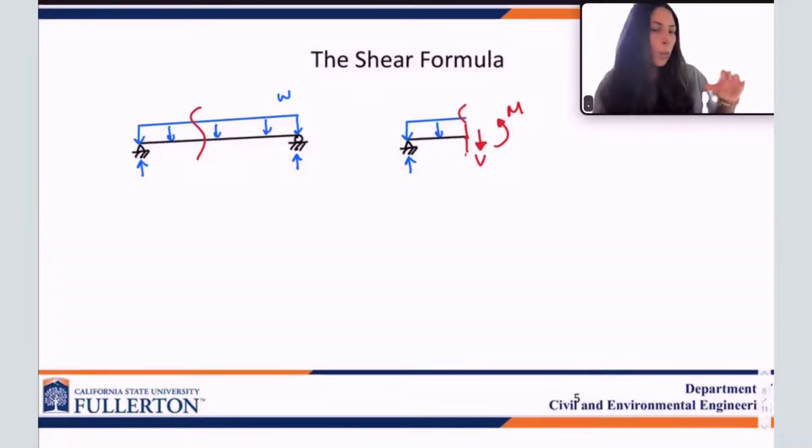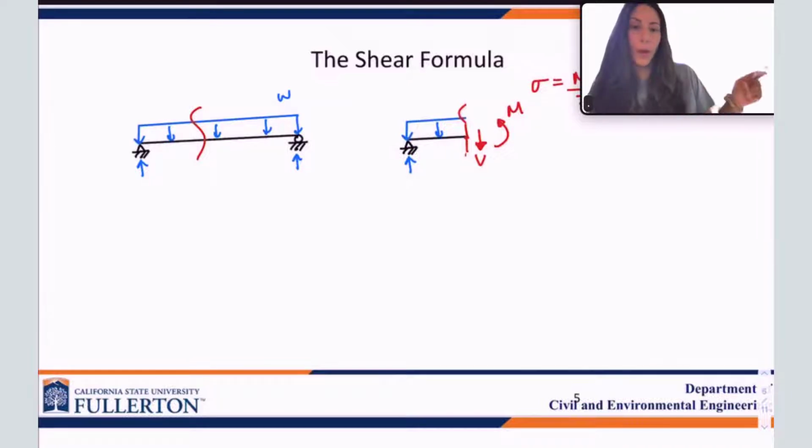have, right? We know from the flexure formula that sigma is equal to MC over I, and there's also another video that already derives this equation for you and shows you an example of it. So if this is unfamiliar, make sure you go back and review that example, okay? This equation shows that sigma, the normal stress in this member, varies linearly along the cross section of the element.